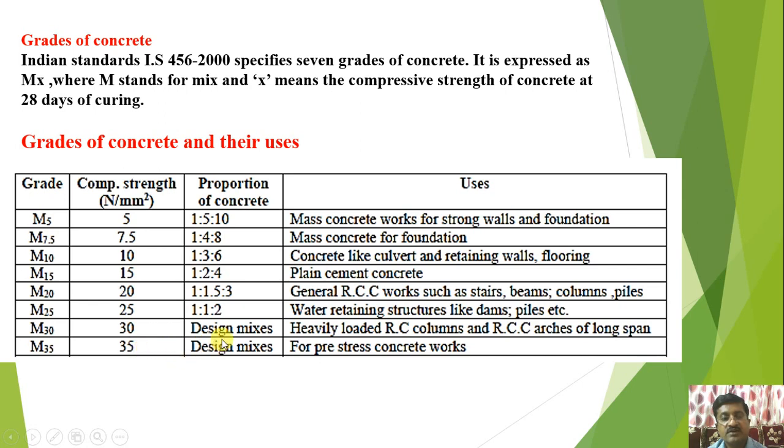Then M30 and M35, these are the design mixes which are used for heavily loaded RC columns and RCC arches of long span. Then M35 is used for pre-stressed concrete works, etc.